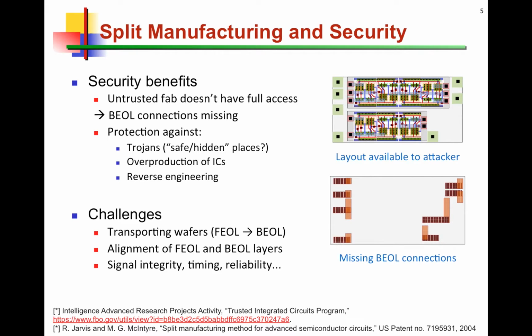So these are the security benefits that split manufacturing intends to deliver. But there are, of course, challenges, and these are mostly logistical challenges. Transporting wafers from the FEOL foundry to the BEOL foundry without damaging them. Alignment of the FEOL and BEOL wafers and layers.